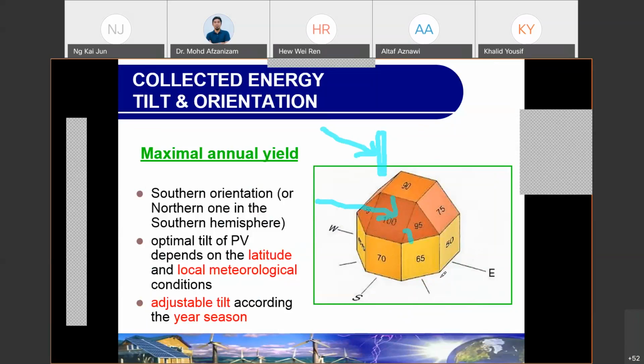So we need to be careful to place our PV module or array according to the tilt angle to get the maximum irradiance. Or else, there's nothing much wrong, but you are just not getting the high irradiance, which means you may need to spend on another PV module, which is costly, to cope with your required power, right?